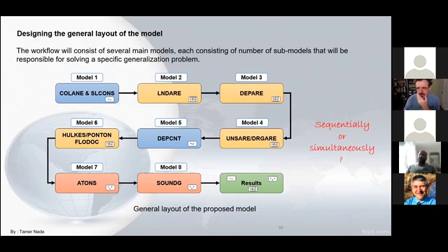Well, that's a great question as well. There are lots of problems, but I believe the inconsistency between the cells is a very important one, because that's where the mariner loses his confidence in the chart when he sees this type of inconsistency between the contours, between the depth areas, and this causes problems in the ECDIS as well. Sometimes the ECDIS will respond sluggishly or slowly, or sometimes it happens that the ECDIS might crash from something like that with the depth contour set to a safety contour, where the safety contour has been shifted, like just the example I've seen. So I believe the inconsistency is one important thing.